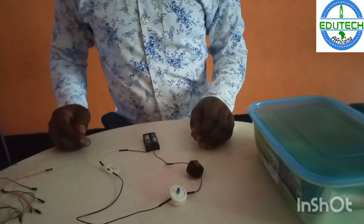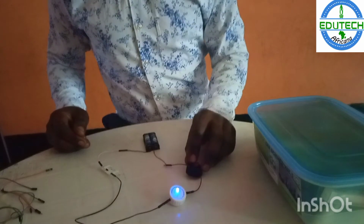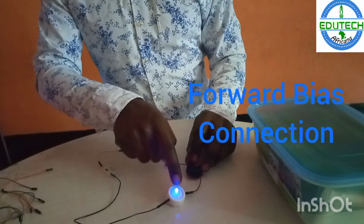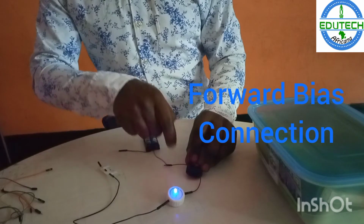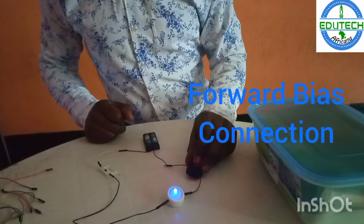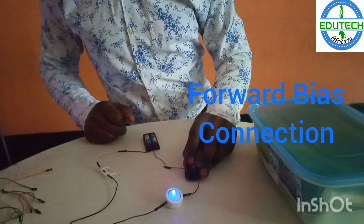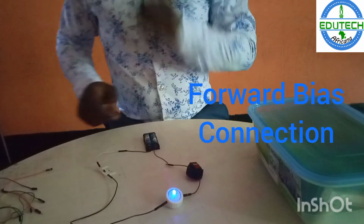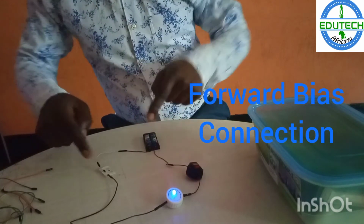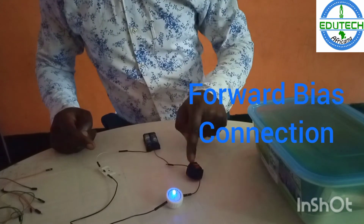So now that everything is connected, let us put on the switch. We see that the bulb lights, but the light intensity is small as compared to when there was no diode in the circuit. So the bulb actually lights, but it's dimmer. So it shows that when the positive terminal of the diode is connected to the positive terminal of the battery, the bulb lights.